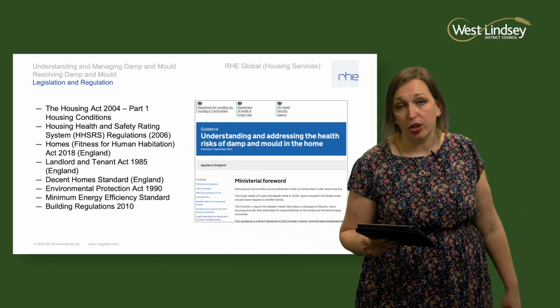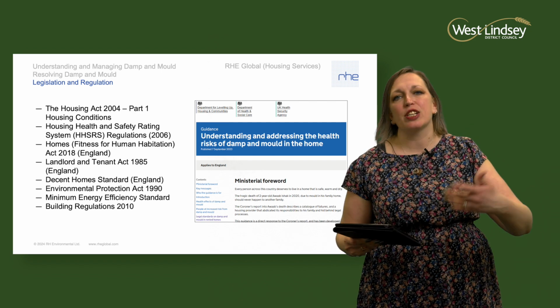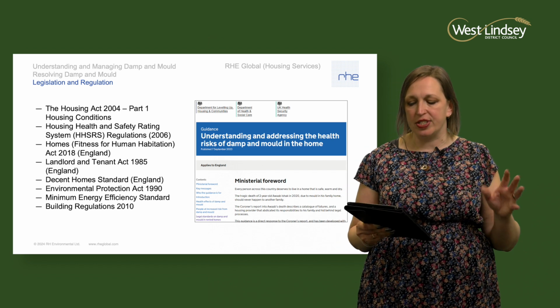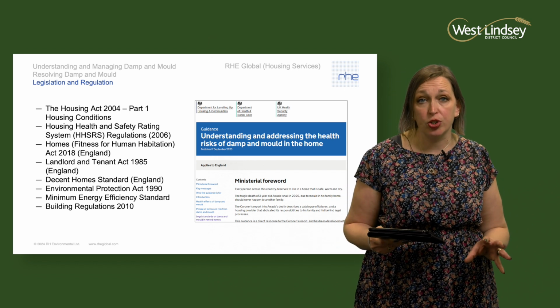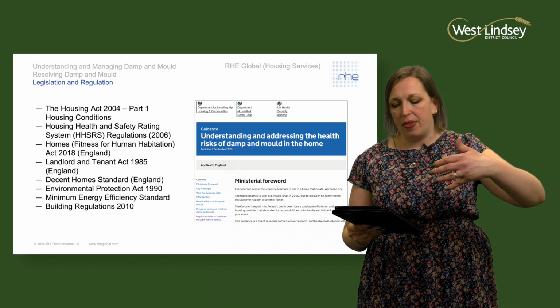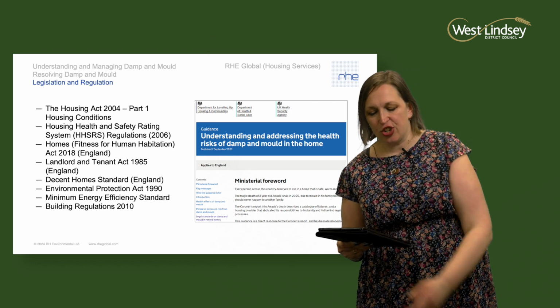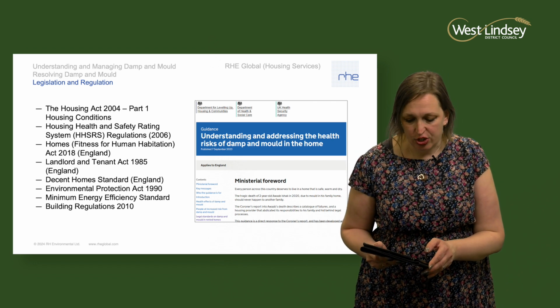They're part and parcel of living in a home. So it's our responsibility as professionals, as landlords, to identify and address underlying causes that are causing moisture to condense on surfaces, and that can be structural issues such as heating and insulation or inadequate ventilation.